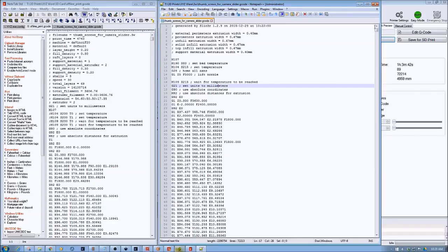In this episode, we're going to take a look at the G-code generated for the XYZprinting Vinci 2.0. While there's been a lot done out there on the 1.0, the 2.0 is the dual extruder version of the 1.0. It has a slightly different size bed and slightly different operating dimensions.